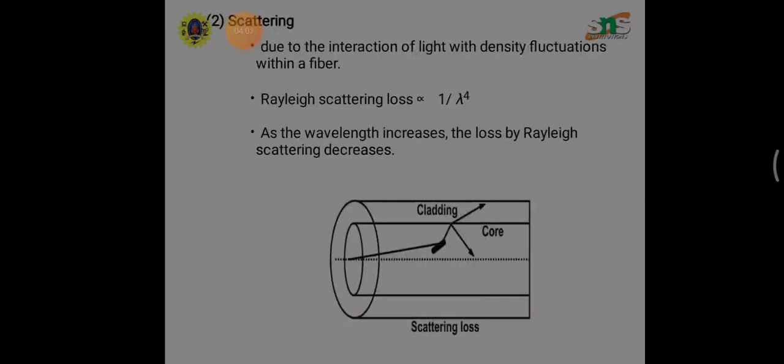Scattering is the process by which some or all of the optical power is transferred into another mode. It occurs when the light encounters a change in the refractive index of the medium. This can be caused by irregularities in the refractive index of the fiber, impurities, particulates or bubbles, or intrinsically by fluctuations in the glass density, fiber axis direction, composition, geometry, or phase state.